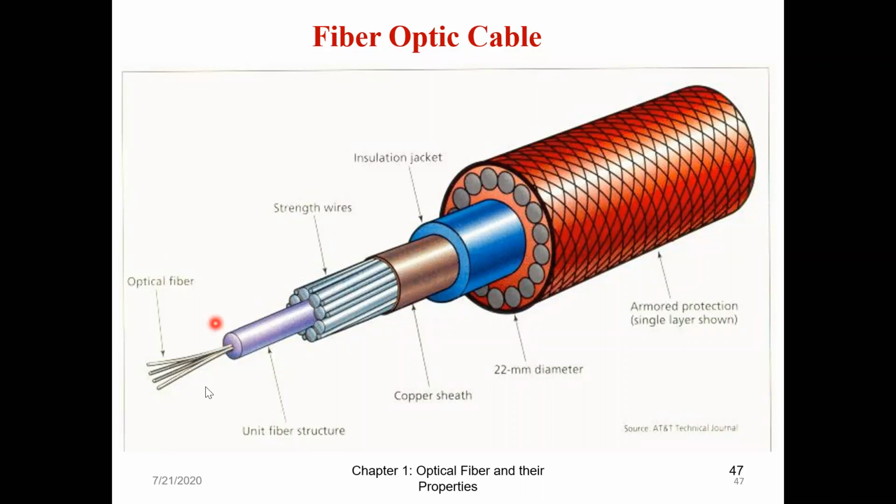So I cannot apply a tight buffer jacket around the fiber. You might feel, okay, let us take a big jacket and the fiber will stay inside. No, see, there are 4, 8, 12 such fibers. If there is a bigger area and you have these thin fibers over here, they will move here and there. So if I have a tight buffer jacket, the fiber might break.